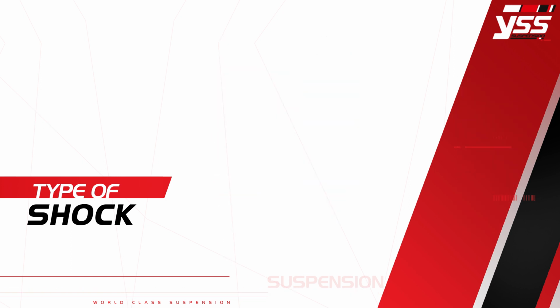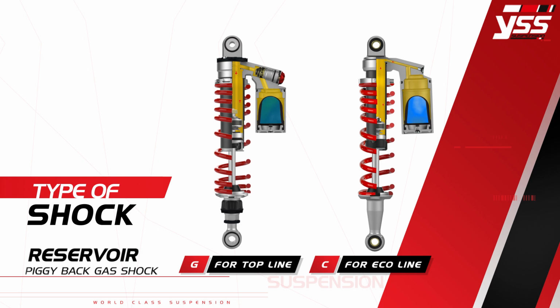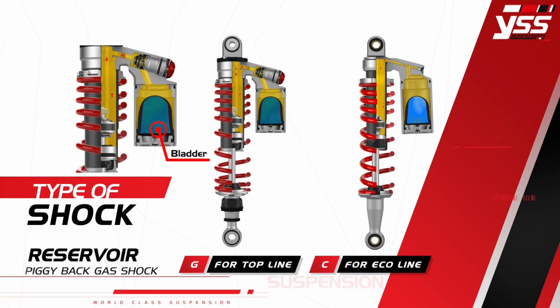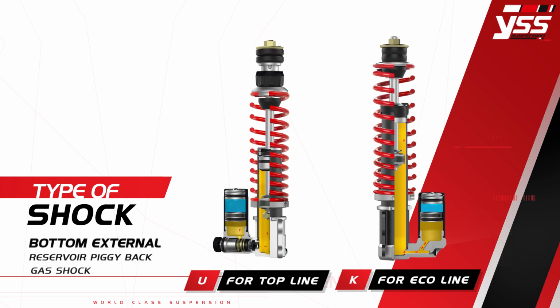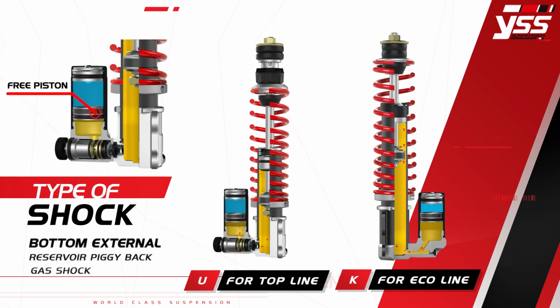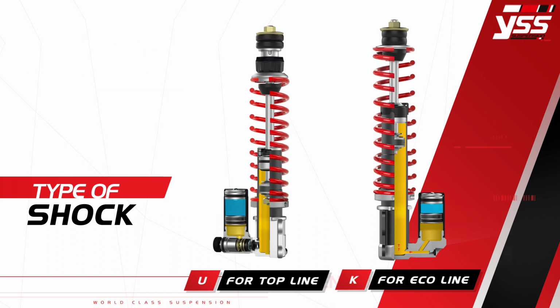It includes reservoir piggyback gas shock, G in top line and C in eco line. This gas shock absorber has a piggyback attached to the shock body, which allows oil to flow through a sub-tank and is able to adjust both rebound and compression. Bottom external reservoir piggyback gas shock, U in top line and K in eco line. This gas shock absorber has the piggyback attached to the bottom part of the shock absorber.